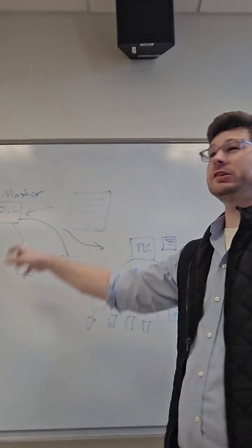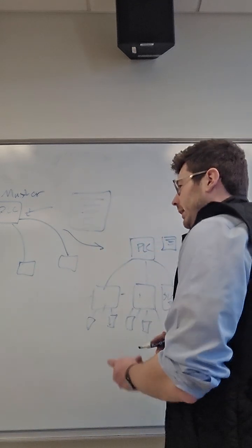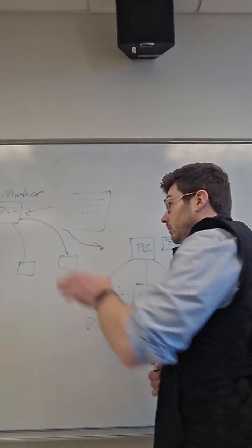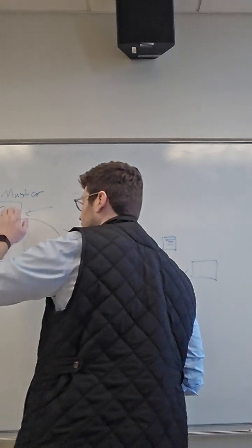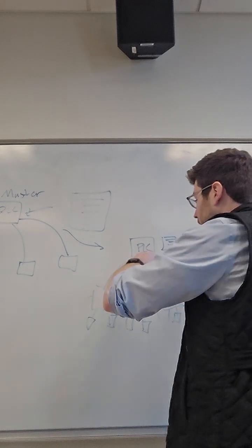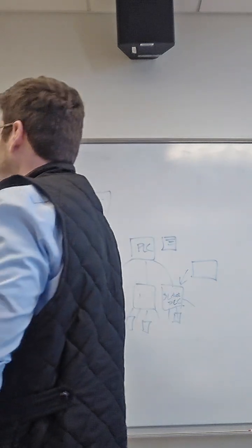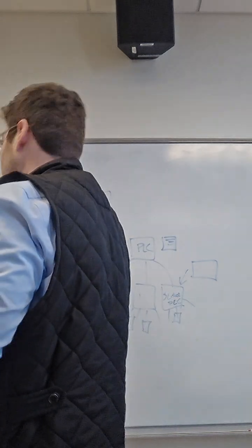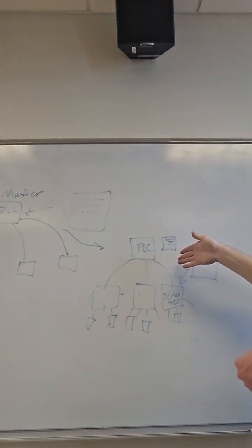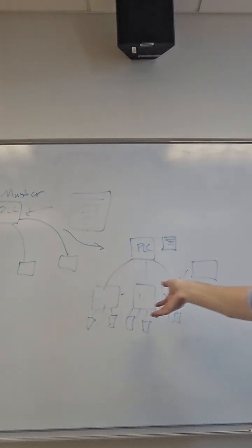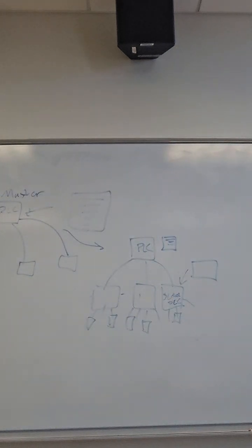This is system architecture in a nutshell. Someone has to decide, okay, this PLC does these things, or this PLC talks to these other PLCs to do the thing. Right? This one might have lower cost but higher complexity. This one might be higher cost. You're buying more PLCs, but it's easier to maintain and it may be a more reliable system. Okay, all things to keep in mind.